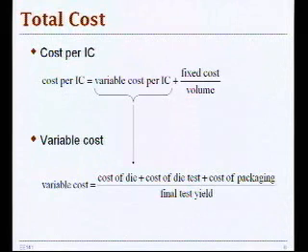So we said that the total cost of an integrated circuit can be broken down into 2 components: variable cost per IC and fixed cost, or non-recurring engineering costs. And from this simple expression, we see that the impact of this fixed cost term can be significantly reduced in high volume products. And we further analyzed this variable cost per integrated circuit that was attributed to cost of manufacturing, testing, and packaging your design, and it was also inversely proportional to the final test yield.